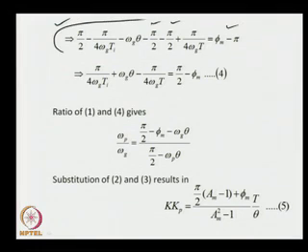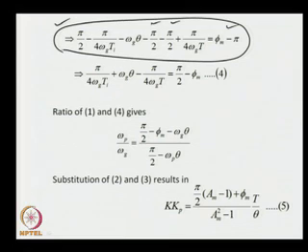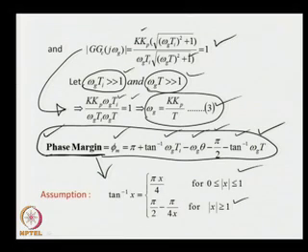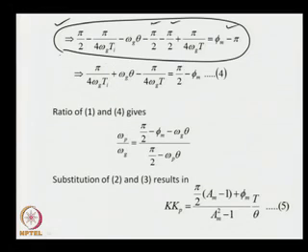This is what we are getting from the expression we have obtained earlier for the phase margin, considering the gain crossover point. Now, this expression can further be simplified and written in the form of pi upon 4 omega g T I plus omega g theta minus pi upon 4 omega g T equal to pi by 2 minus phi m, giving us equation number 4.